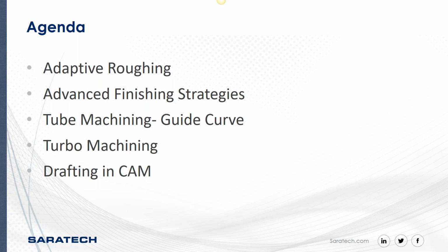We're going to be talking about the adaptive roughing operation, the advanced finishing strategies that are new to NX12, the tube machining with guide curve, the turbo machining, and then now we have drafting in CAM. Before we weren't able to connect the CAM module to the CAM side. Now we can go into the CAM side and do all kinds of neat things with work instructions.